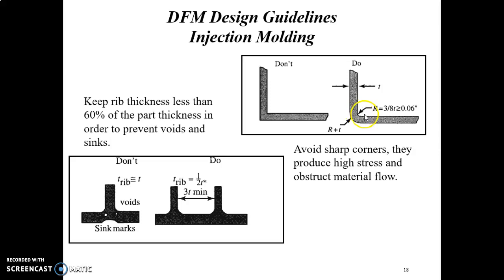Accordingly, it is about 150% of nominal wall thickness. Sharp corners at the base of bosses and ribs can be stress concentrators. The edge where a boss meets the nominal wall should be rounded to reduce the sharp corner without increasing the wall thickness enough that it creates a sink problem.